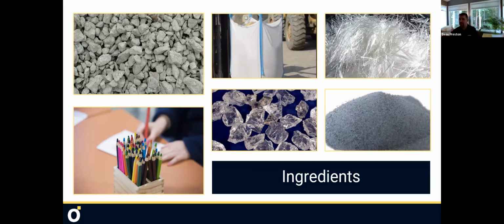exceptionally resilient, with an impact rating, and they both have the absorption level of porcelain as a result. So that is dozens of times less absorptive than fiber cements. Okay, so they're not going to ghost and do that. They have, again, the capabilities of porcelain. And because they're that way, they don't hygrothermically cycle the same way. They're not expanding and contracting because the moisture in the air is absorbing into them like some panels do. Thermally cycling they do, but much less because of their makeup.